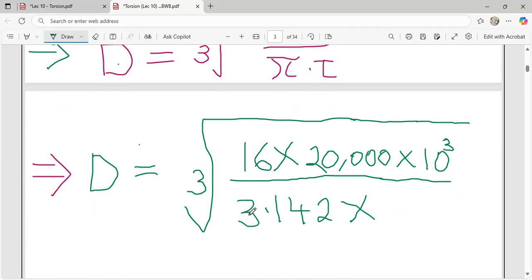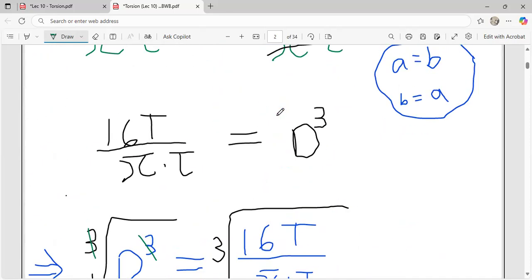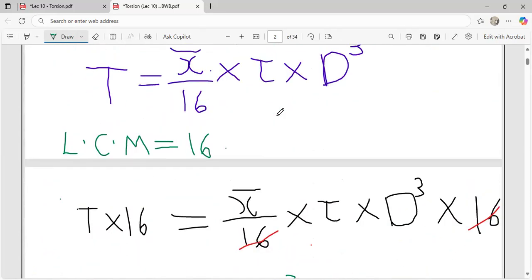The value of the shear stress was 40 Newton per mm squared. Because this 40 is in Newton per mm, the torque must also be in Newton mm for precision purpose. They must all be in the same unit. Else, if they are not in the same unit, you can't solve it, and your answer is not precise. That is how the law of physics works.